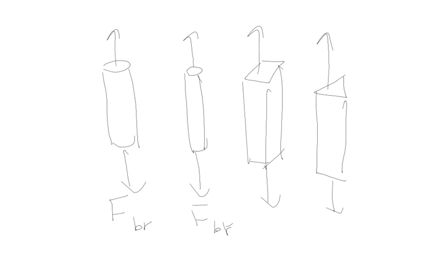Let me ask you this. If I take these 4 breaking forces, are they going to be the same? The answer is no. So even though these are all hot rolled steel or cold rolled steel, whatever the case is, even though these are all the same material, they're different size and shape. So they're going to break at different forces.